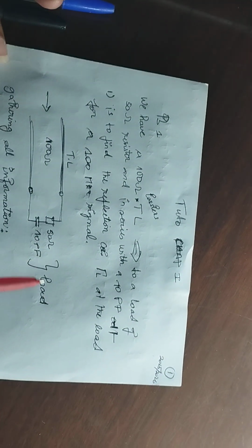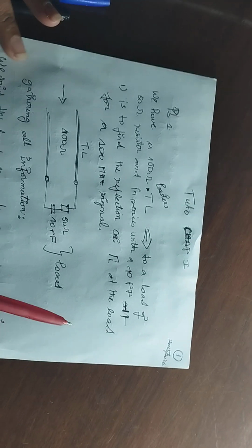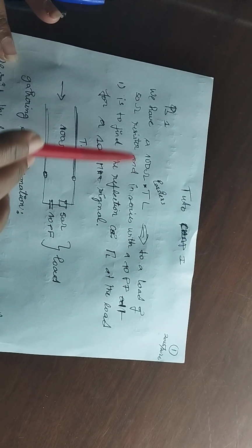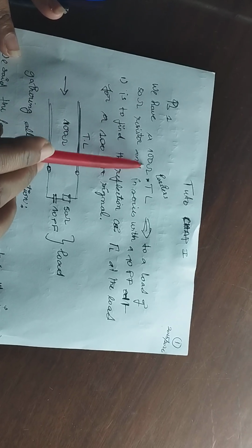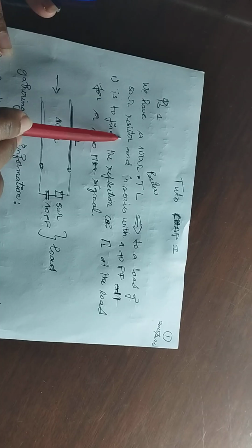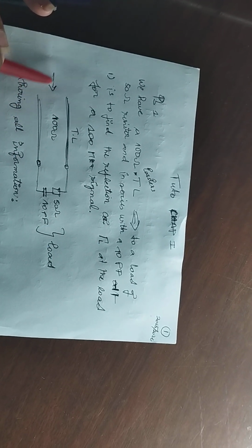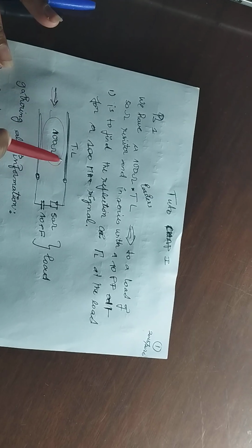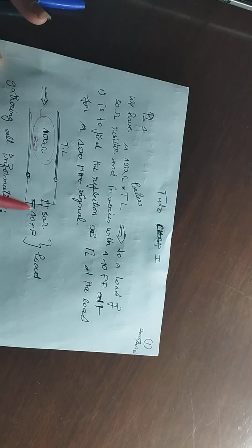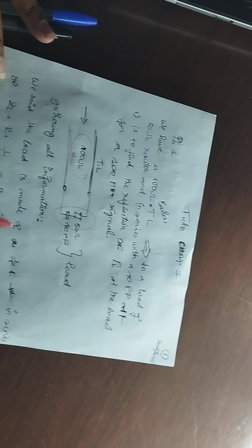So I'll just do a small tutorial, two problems for you to have fun and try to go through. We have a transmission line of 100 ohms, as you can see, connected to a load of a 50 ohm resistor in series with a 10 picofarad capacitor. This is the input here, this is the transmission line with Z0, of course, the characteristic impedance, and this is the series load. Now, gathering all the information, you can see here we have